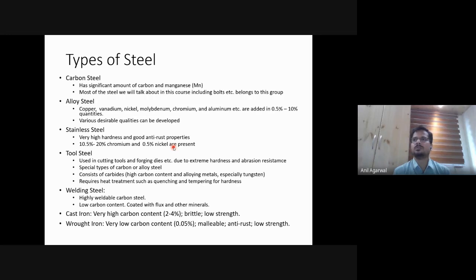So diamond is not the strongest material. It is the hardest material, right? Hardest material basically means that when a material has some kind of crystalline structure, the crystal shapes are such that it's very difficult to chip off a few molecules from the edge. Diamond has that, but graphite does not. Graphite is very easy to chip off. Both of them are made of carbon, but the molecular structure is such that graphite is very easy to chip off, whereas diamond is very, very hard to chip off, right?